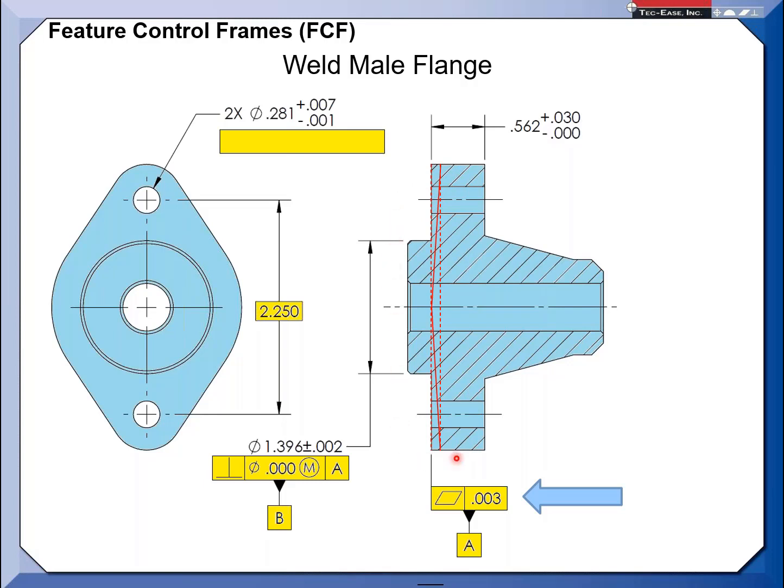When the machinist was machining the flange, the door, in his process, I asked to go down and qualify the sealing surface. It was 4 foot diameter, 48 inches, and I had to have a flatness of 5 thousandths due to the compression O-rings we were using. So when I went down and inspected what the machinist had done, I had a requirement of 5 thousandths, but when we actually measured the surface, it was within 1 thousandth. I was like, wow, I'm pretty pleased. So I said, okay, finish up machining and send it on its way.